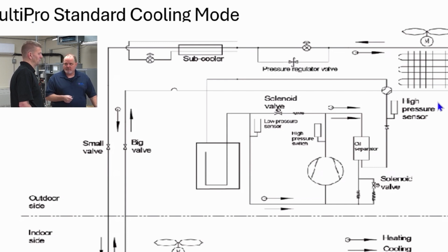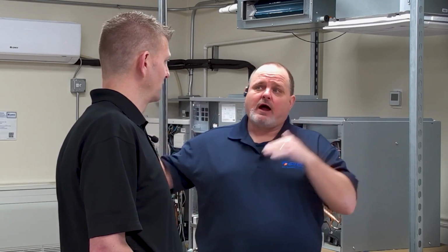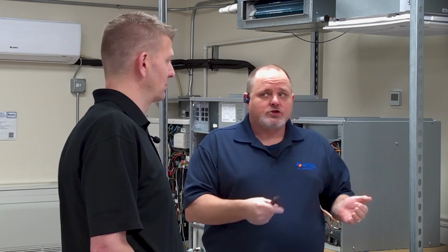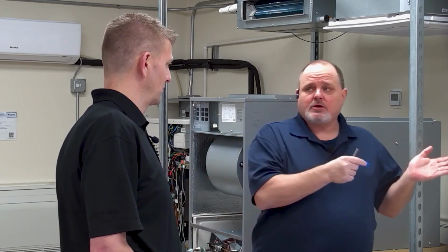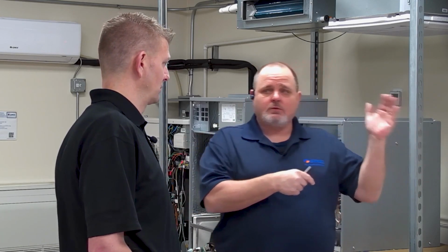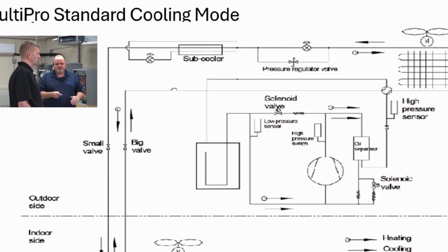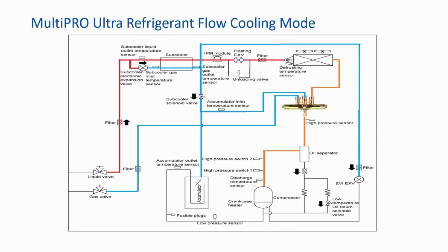Okay? So just because you've got a restriction, and this is where I've seen a lot of guys go wrong with that in the years that I've been troubleshooting and dealing with HVAC equipment and refrigerant flow issues, everybody always wants to think that if I've got a restriction, I'm going to have high pressure. That's not always true. You may have high pressure to start with, but once that liquid backs up within the system, it can't move anymore, head pressure drops. So, all right, moving on.